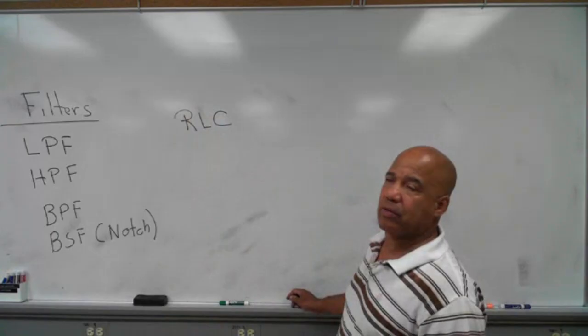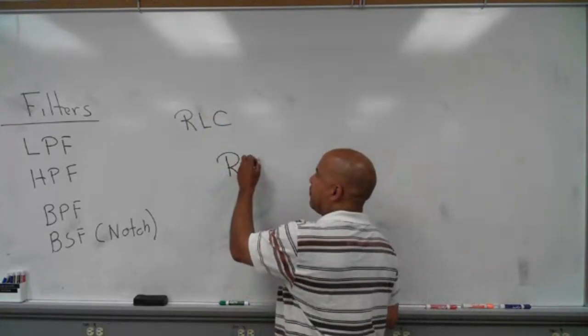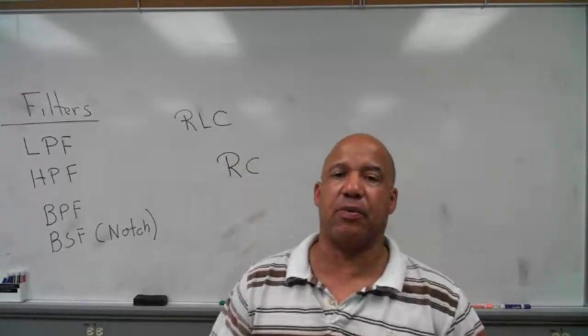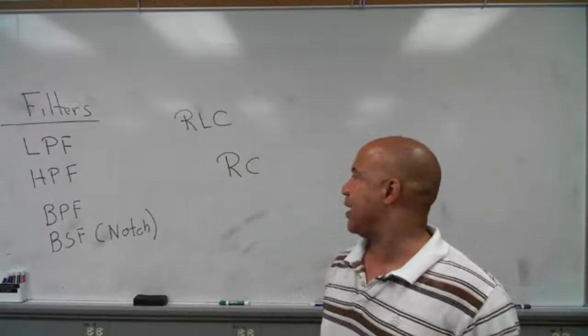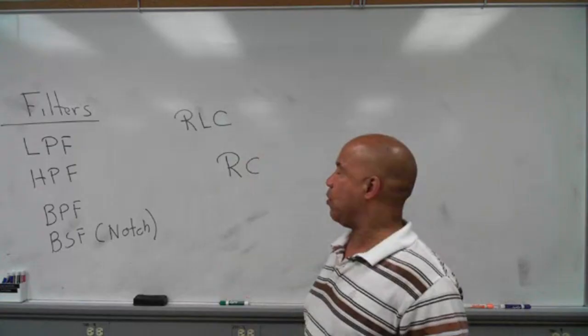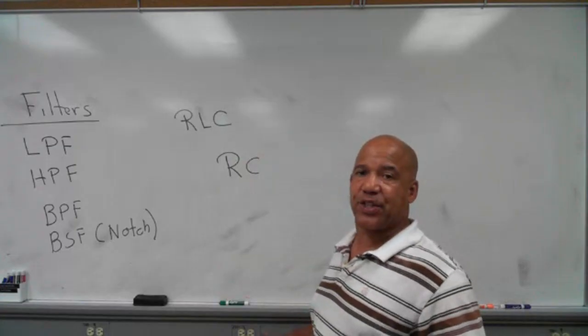What we learned about was the RC filter because it's a simple filter to understand. And then filter action as it applies to an RC circuit, we talked about that. The fact that for high frequencies, the capacitor acts like a short. For low frequencies, the capacitor acts like an open. We call that filter action.